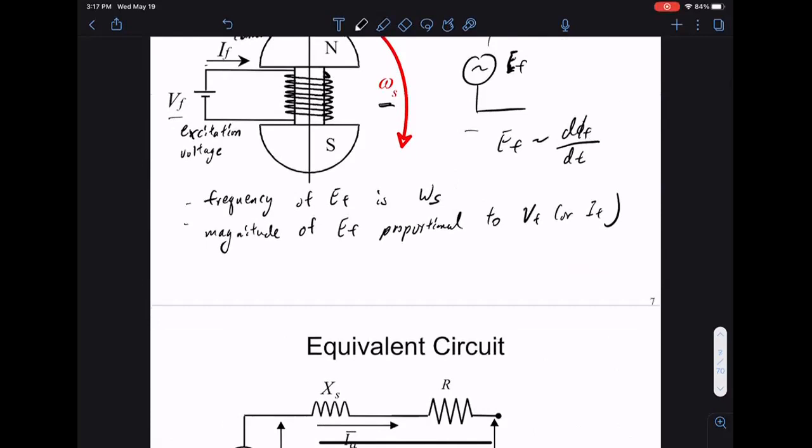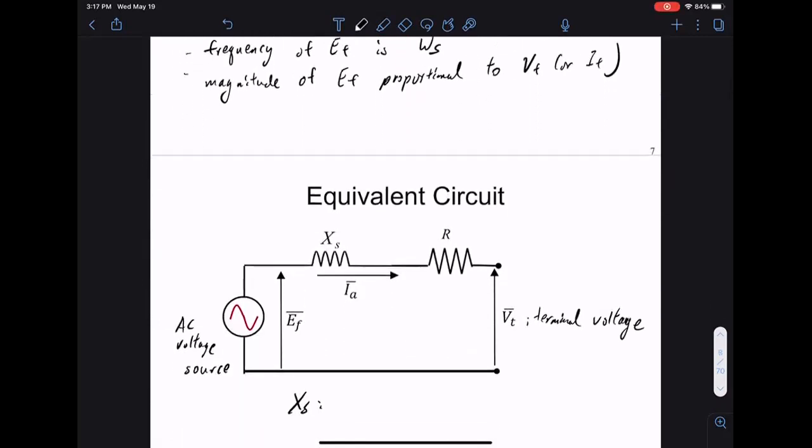They show up as this reactance. And so this reactance you can think of as the representation that lumps all these coils of wires together. This is our XS. This is called the synchronous reactance because this is a reactance that's coming out of the generator.